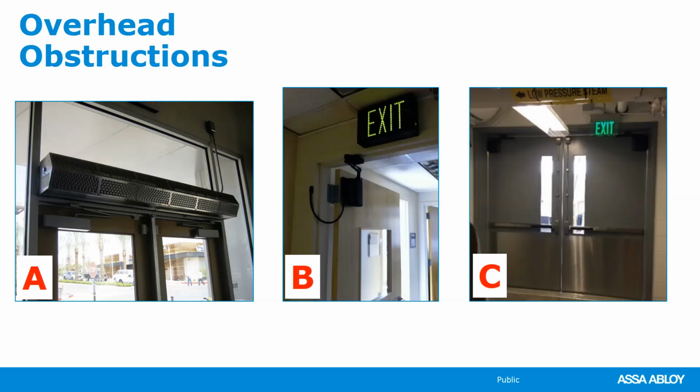And then on opening C, an example of just multiple obstructions that I was able to find. There's actually an exit sign, that overhead pathway lighting, that fluorescent lighting is actually in the way of a 6-inch box. It goes right up to the edge of the door. There's even a steam pipe over on one side. And there's also the deep reveal. So, somewhat difficult modifications to make in C, very easily solved through the use of a door mounted operator.